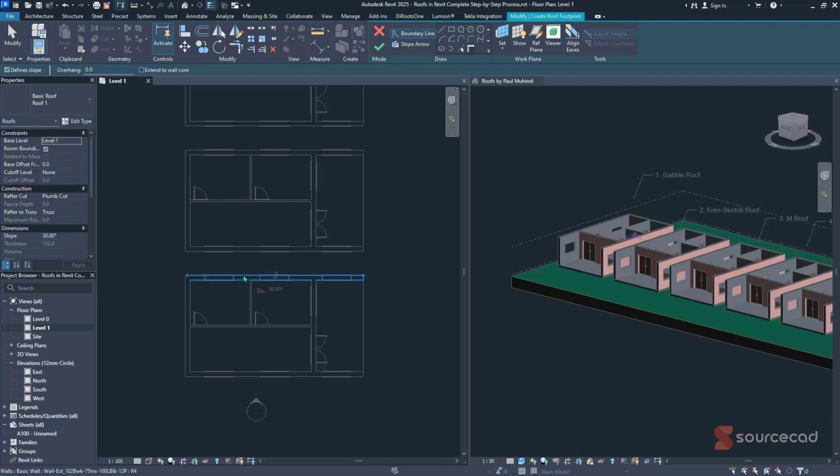So this is one wall, and you can clearly see a magenta line has been created. Then the next, I'm just simply selecting the walls. So over here, I want the roof to extend to this level, but because this is not a wall, as you can clearly see, it's just an open extended area, we need to change the selection option. So I'm just going to simply click on that option, then click on that point, then at this other point. Additionally, I can just opt to delete everything by just tab select.